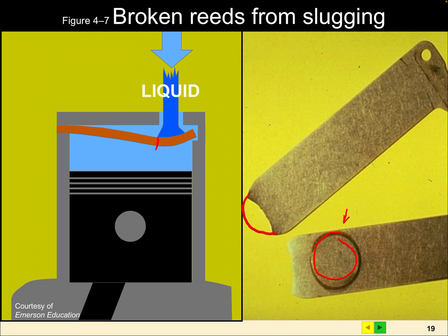The way we minimize that in all of our systems is we try to have some superheat. We try to have a very minimal amount of superheat to maintain efficiency, but enough to make sure that we don't have any slugging. And that can be really, really damaging. Slugging is simply when you have liquids that go into the pistons and create some damage.